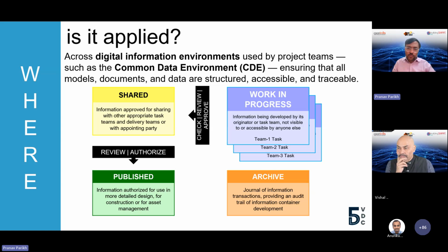Now, it may sound very complicated, but most common data environments take care of that today. And you take care of it by creating your folder structure around the CDE guidelines. This is one of the major intentions of ISO 19650, and how you make sure that we all talk the same language. Because now when we go to the common data environment where all the documents are, we know which folder we want to go to, right?